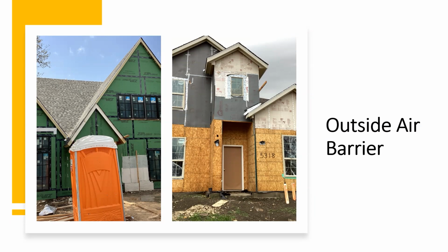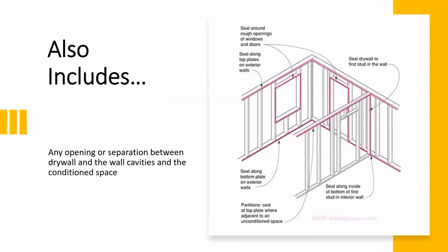So we see the OSB is being overlapped by T-ply. Is the T-ply stapled correctly to the OSB to where it makes an airtight seal at that point? If not, it needs to have some kind of tape there, some kind of air sealant there. And then when the seams butt together, they're taping that as well, but they also still need to make sure that they nail that per the nailing pattern required by the manufacturer.